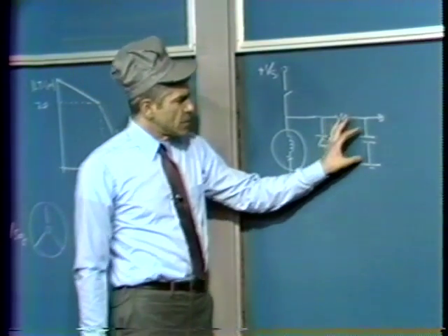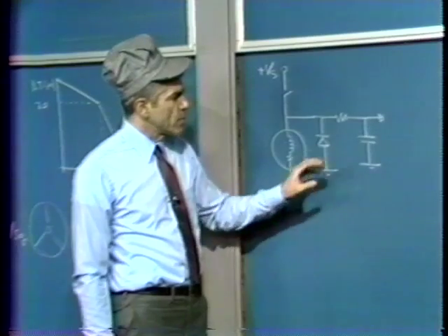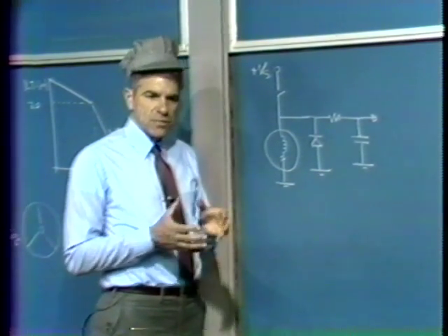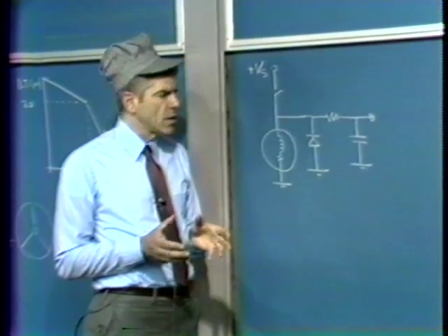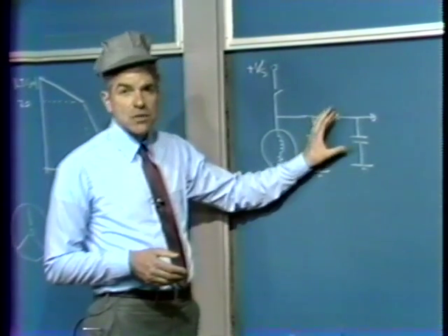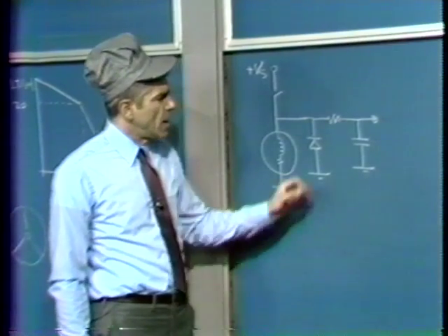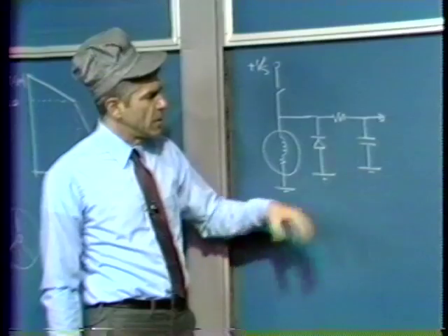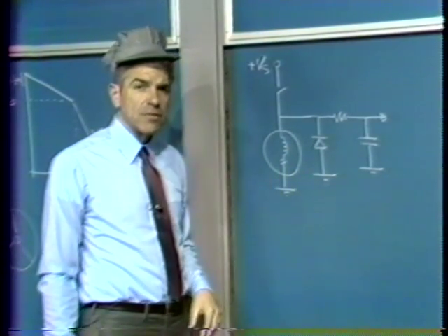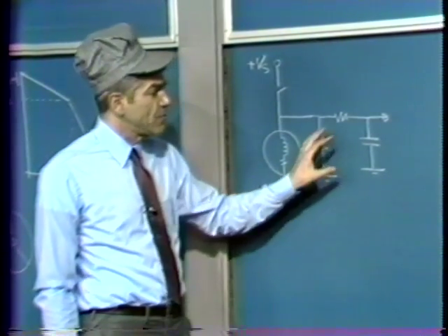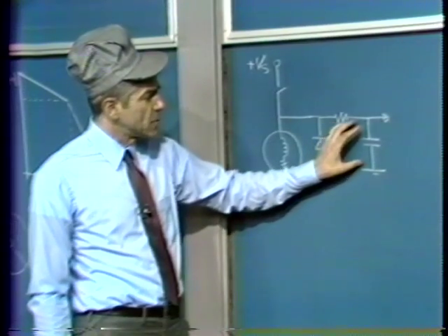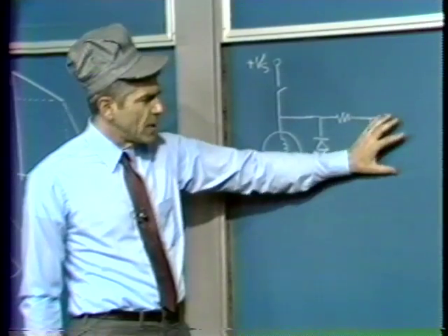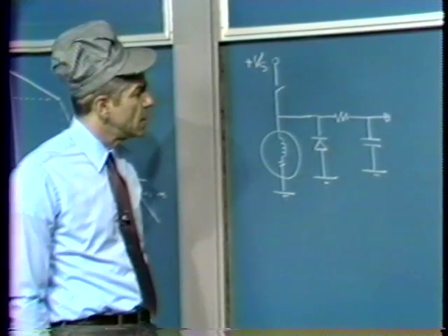And by using a smoothing network here, again recognizing the very great difference between the frequencies of interest for commanding the motor, which are several hertz, and the switching frequency, which is 100 kilohertz or thereabouts, you can very easily use a slightly more sophisticated network in here, and get lead kinds of characteristics out of the power amplifier. The place where I actually do the amplifier compensation is in the power amplifier, by an appropriate modification of the elements in this portion of the network.